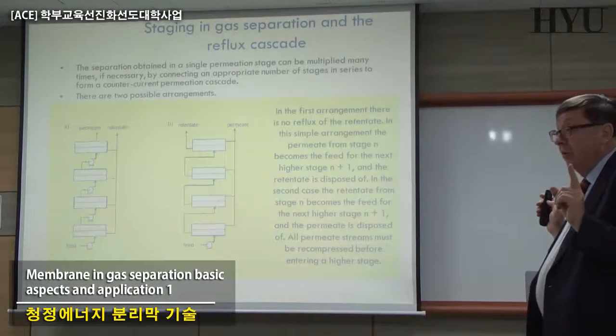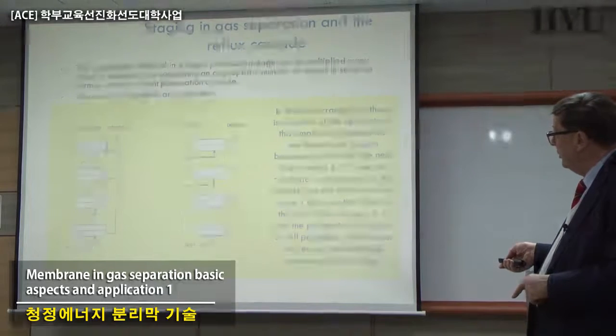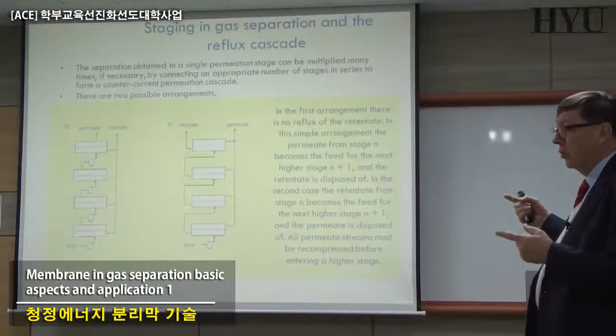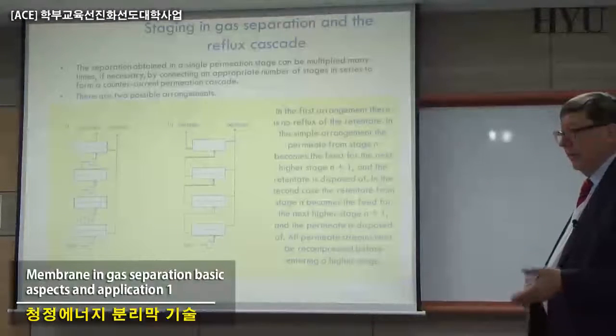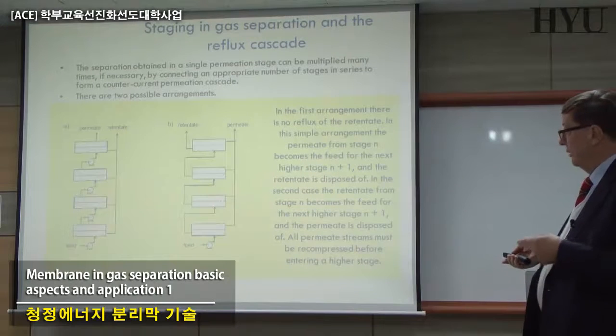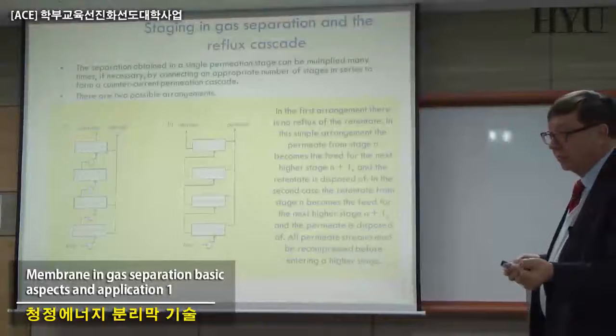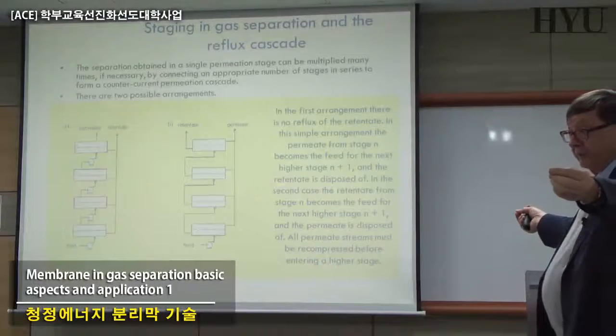In this case, in principle, the problem exists, but you compare the length of one module with the length of another, not between the two configurations. Between the two configurations, the only difference is whether you are working in counter-current or co-current, which makes a big difference in terms of length.